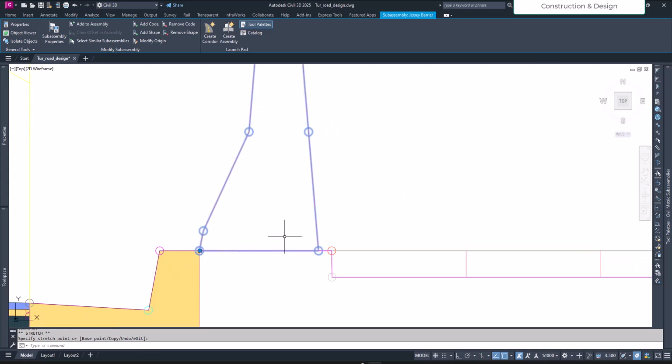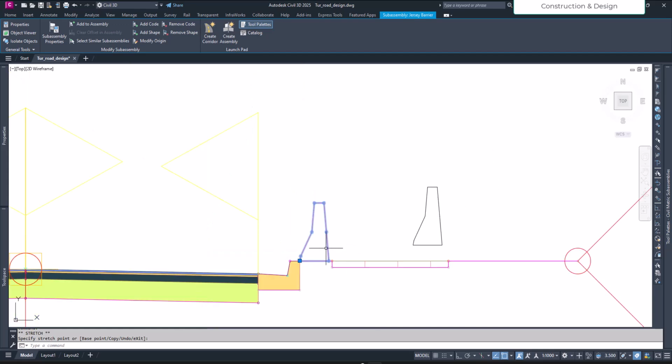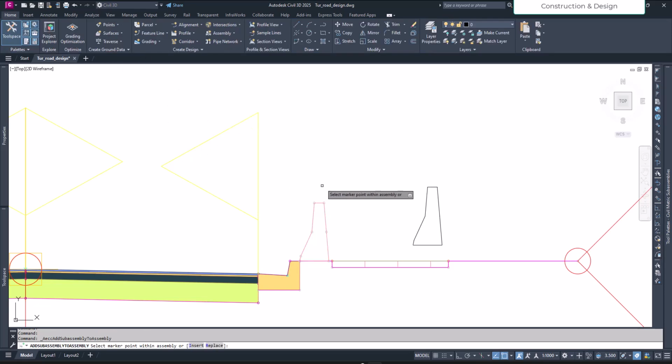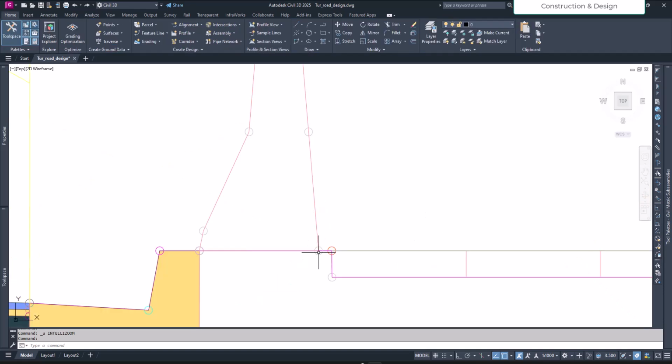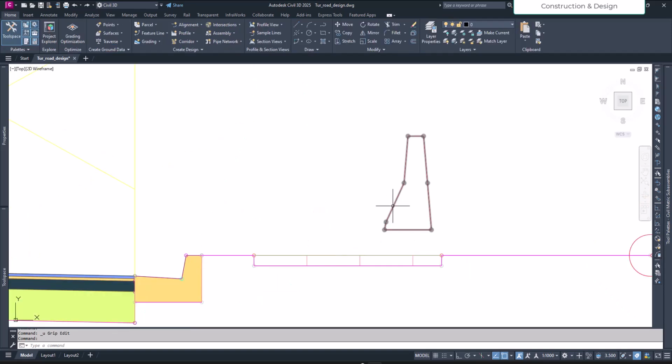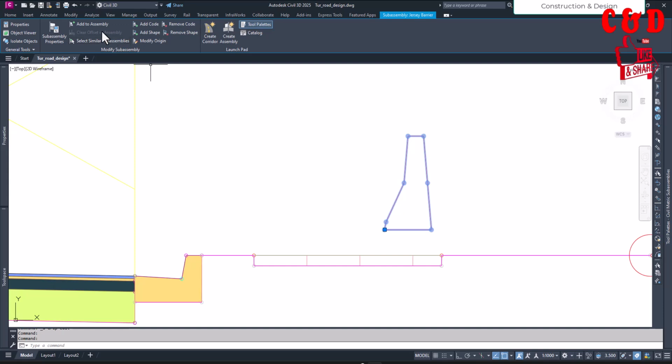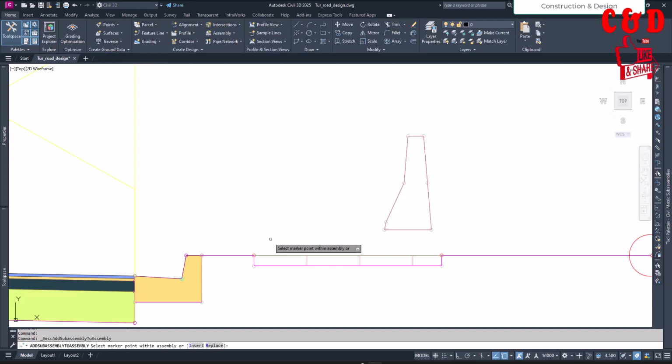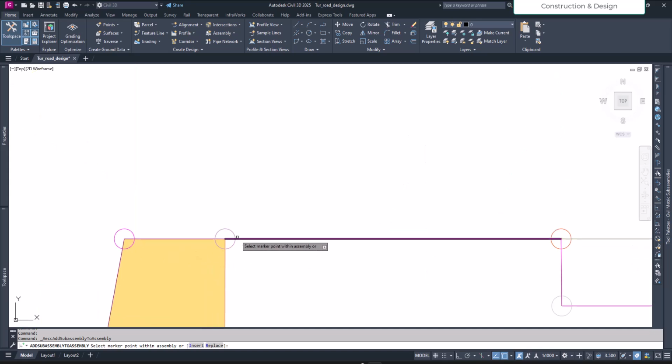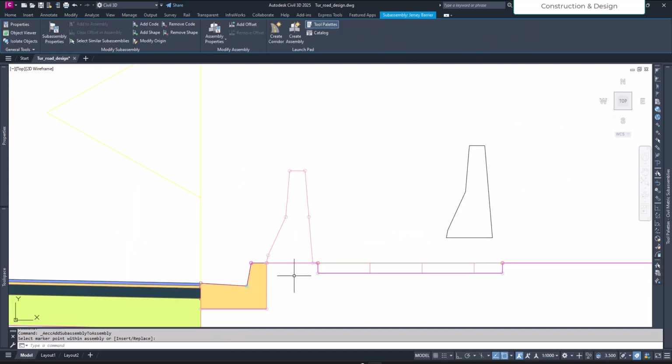Okay, and now with this selected, I say add to an assembly. Add to assembly, and where I want to add it. Even if we don't move it, let's say go back. It's here, and we just click on it, and then we say add to assembly. So where I want this point to begin from, this is the origin. If I click on this particular point, you see how it automatically moved to this location.